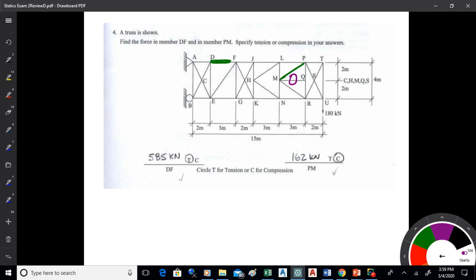I don't. So that's my point. I can't tell that it's zero force when I look at M. The only place I can see it is at Q. It's an unloaded T. So if it's zero at Q, it's zero, even though it's quite clustered at M. So I've proved it at Q, I'm done. I know it's zero. You all with me there?